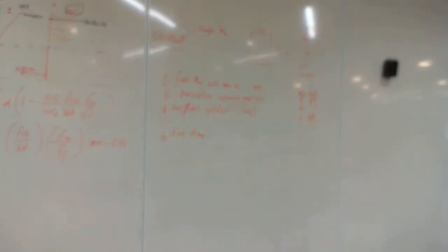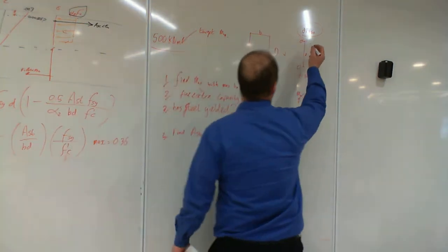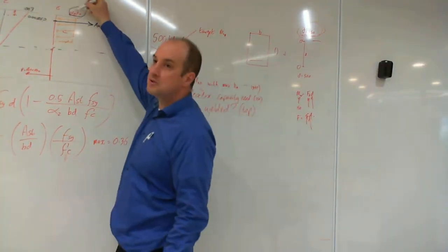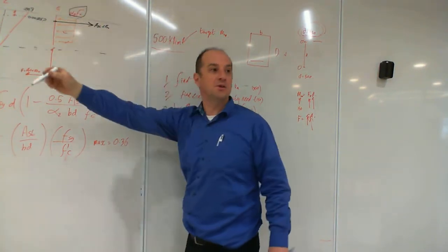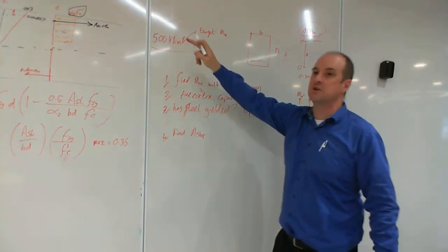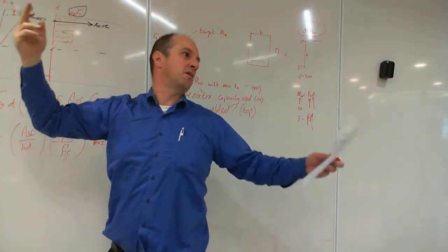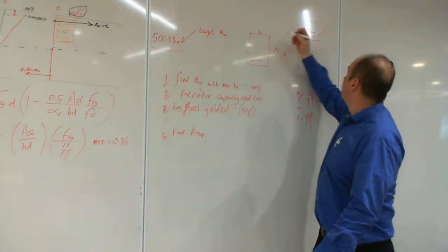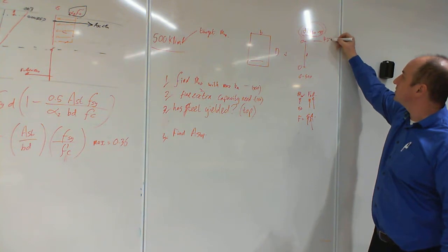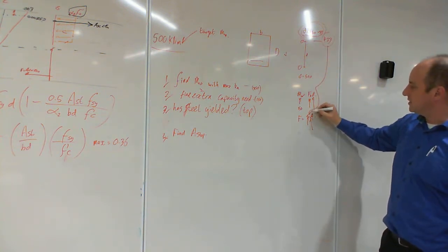But before we do that, we have to subtract off that 450 minus the alpha 2-FC. So let's put some numbers out of the air, and let's say that alpha 2-FC, if it was 32 MPa concrete, and that was 0.85 times 32, is 27. 450 minus 27 is 423. That 423 goes into there.